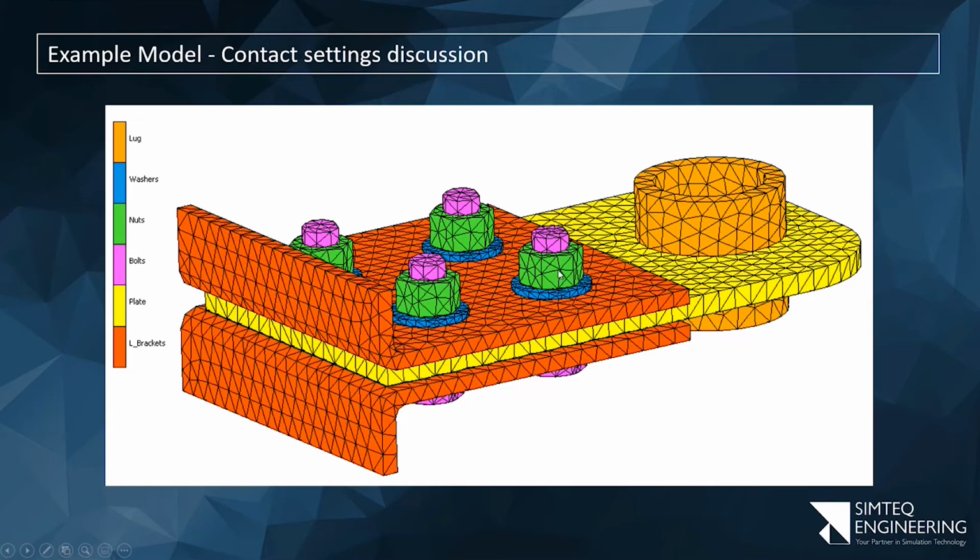So which mesh is finer between these two parts? That's a lot harder to say. You'll have to zoom in a bit. It's not that clear. I think the green is slightly finer on that interface than the nut. Sorry, the nut compared to the shaft. So in that case, assuming this is slightly finer than that, I'll make contact from this one to that. If I look at the sequence there, this will be the first and the second body, simply because that's the order it lists them. So I want first to second if this one is the final mesh.